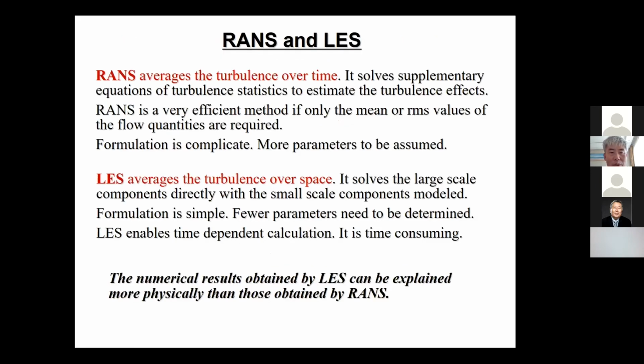So, comparing RANS and LES. RANS averages turbulence over time. It solves several turbulence equations to estimate the turbulence effect. It's a very efficient method if you want to know the mean value only. Especially for wind environment evaluations, if people consider the pedestrian wind speed, they consider the mean wind speed only. So RANS is a very strong tool to get a result. It's not as accurate as LES, but people usually accept the result of RANS.